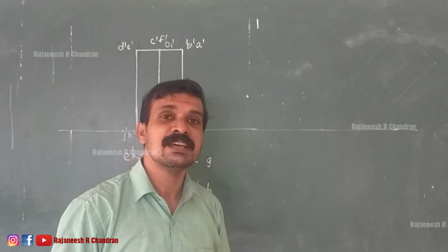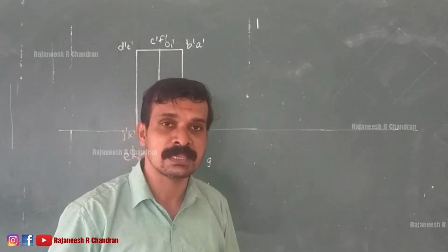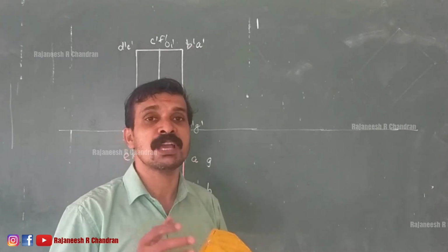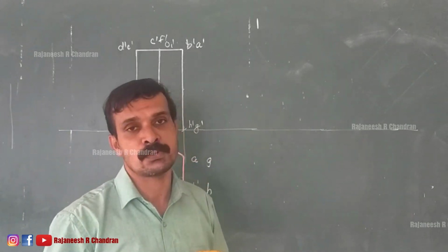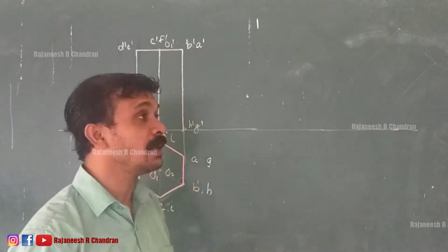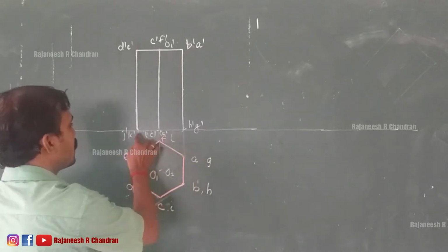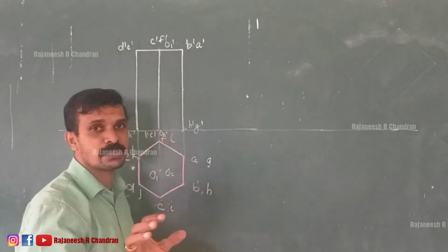So we know that when the axis of a solid is inclined at an angle of 45 degree with the HP, we have to redraw the image with the base inclined at an angle 90 minus 45. Since the angle is 45, 90 minus 45 again becomes 45. So the easiest method is we can tilt the base at an inclination of 45 degree, right?